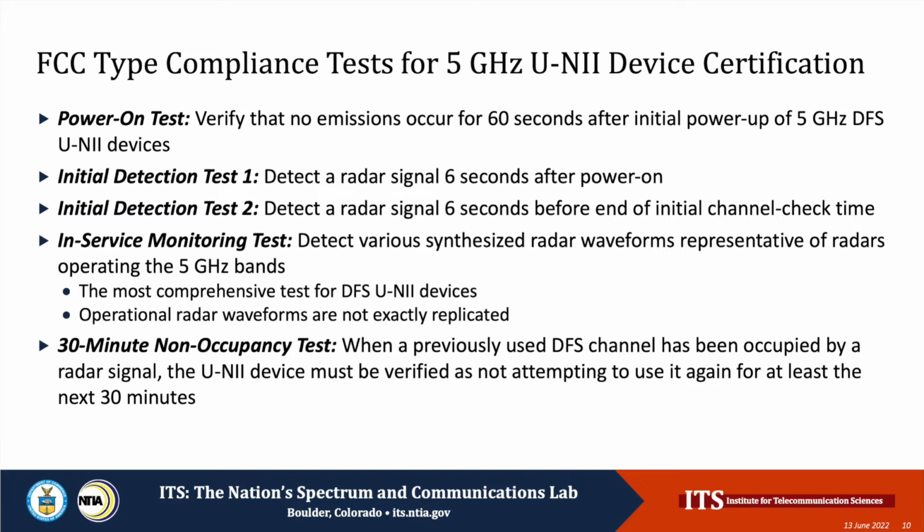And then finally, in the certification series, there's a 30-minute non-occupancy test that we have to show is successfully passed. This test is used when a DFS channel has been occupied by a radar signal. Once that channel is occupied by a radar signal, the UNII device is not to attempt to use the channel again for at least the next 30 minutes.